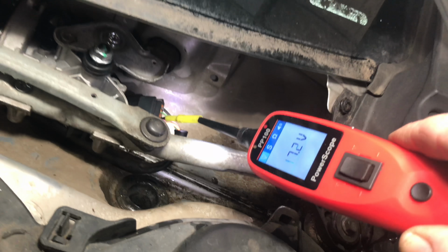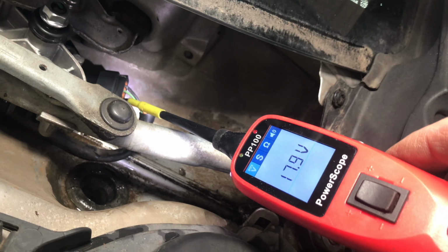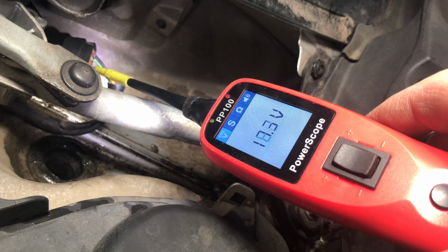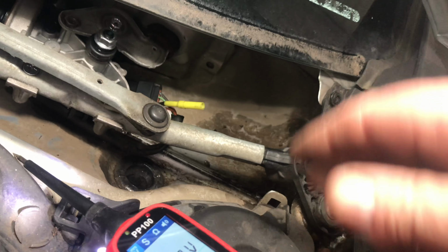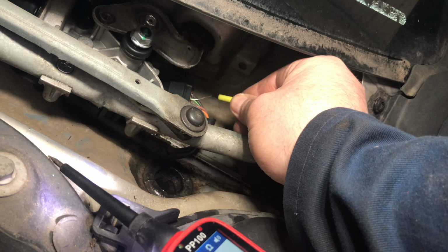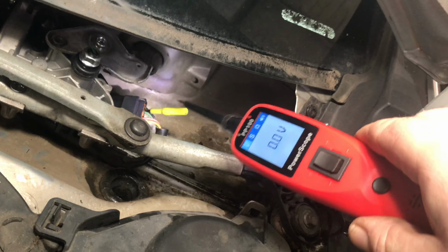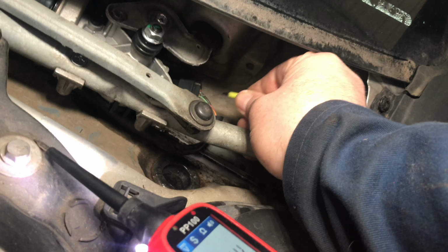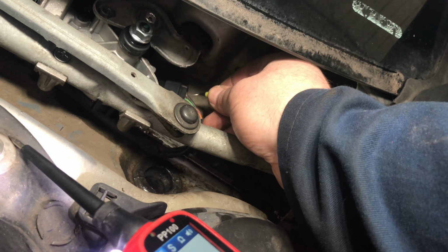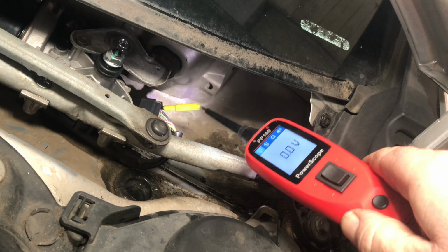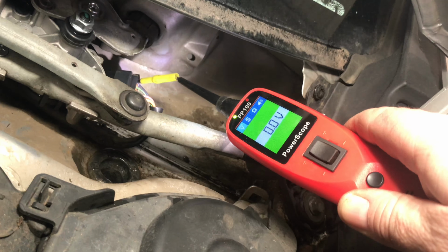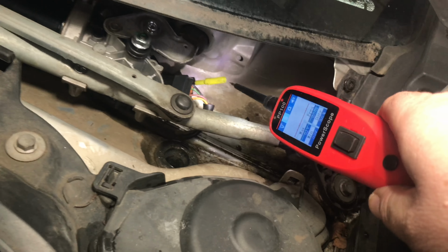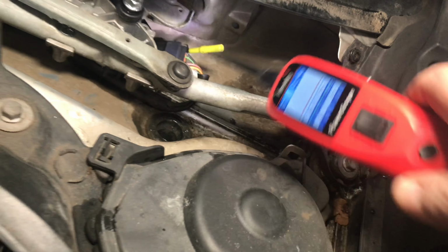Oh, look at that. I thought, funny looking voltage, that. I thought that was the ground as well. Ooh, 18 volts. My goodness. You'd want to get the scope on that. 12 volts on the green wire. This is at full speed. And this must be a ground, this last one. So ground. I'm seeing we could get a scope out, we can use this thing. Let's check that. That's a solid ground.